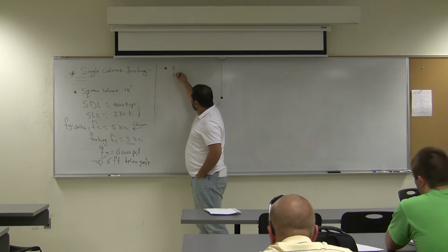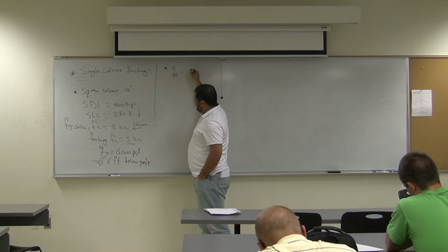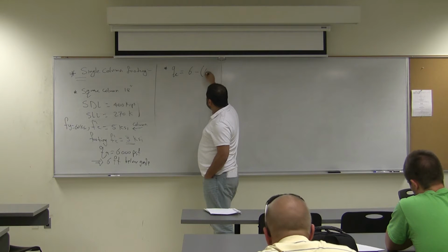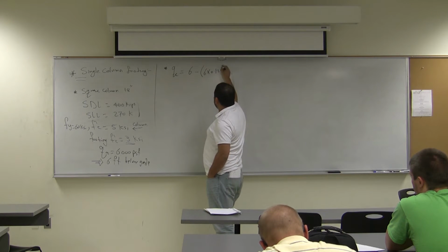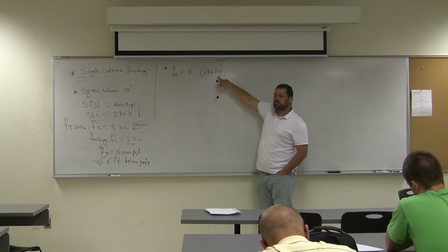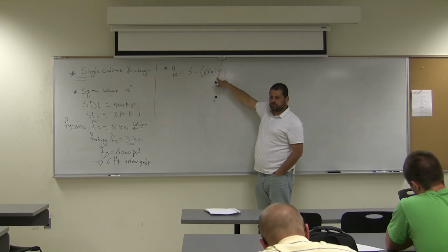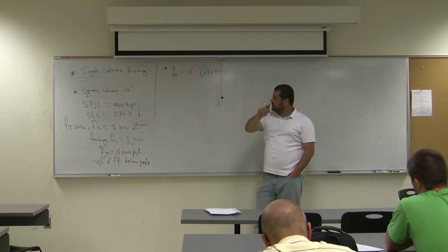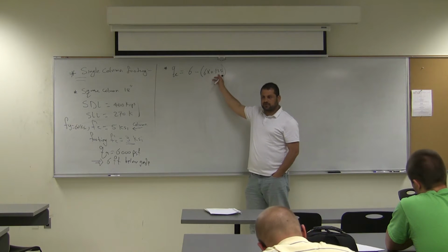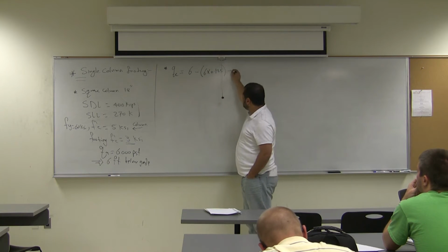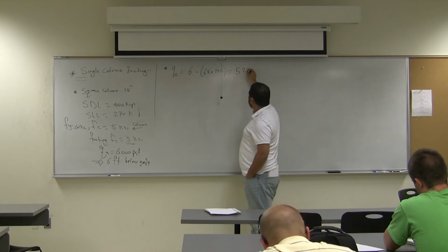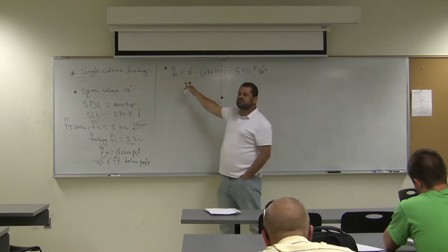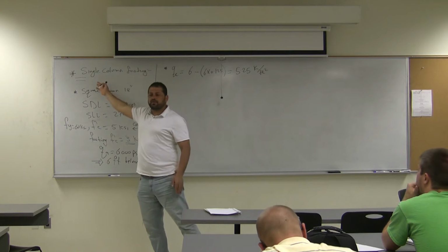So Q effective equal 6 KSF minus 6 times 0.125. Again, this 0.125 is 0.125 kip per cubic foot. Okay? That's the unit weight. So you multiply by the height, you get it in kip per square foot. You subtract from 6 kip per square foot, how much you get? 5.25 KSF, or kip per square foot. That's what's effective for supporting the load coming from the column.